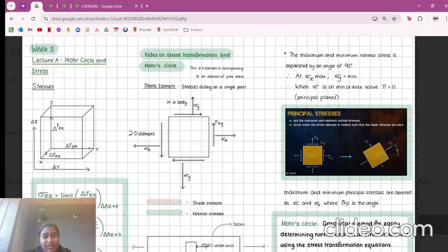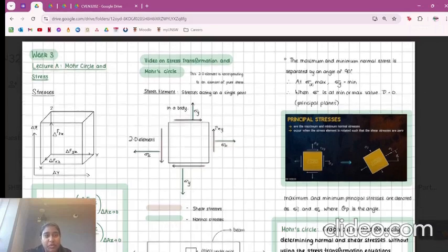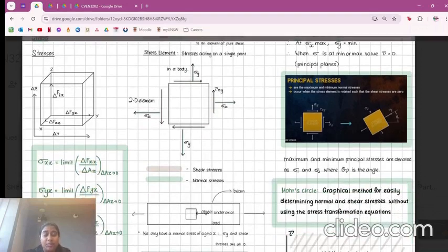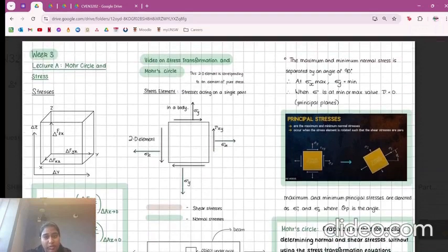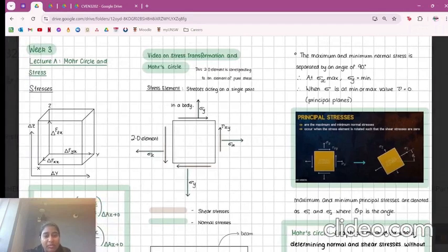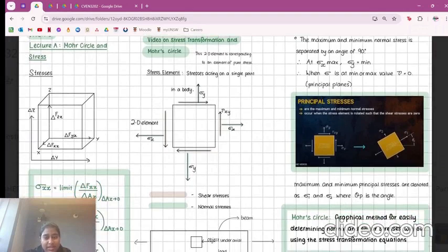So this is where we get introduced to stresses in soils, and how we can calculate things like the change in stress or the stress on a certain point in the soil at a certain depth. And then we'll also look a little bit at soil when there's a flow of water going through the sample, in which case you'll have to calculate things like pressure head, which we'll cover a little bit of in this crash course.